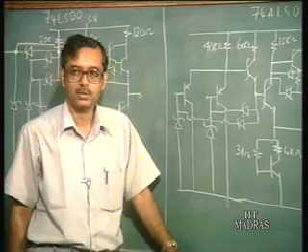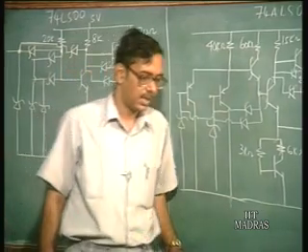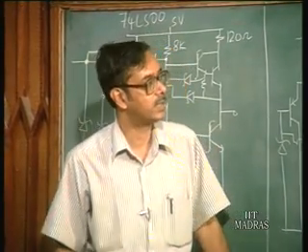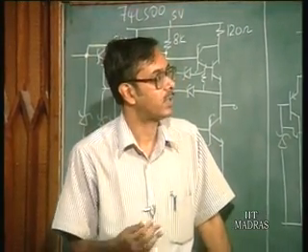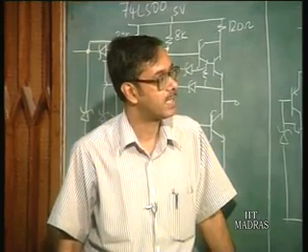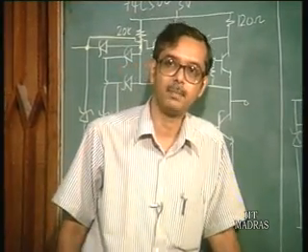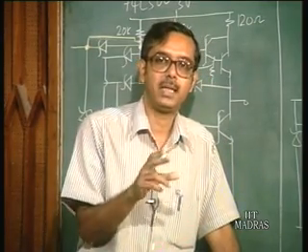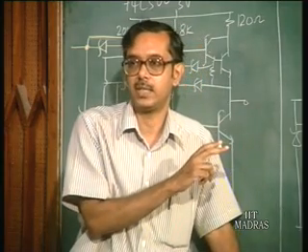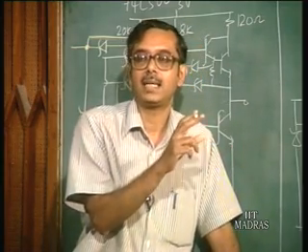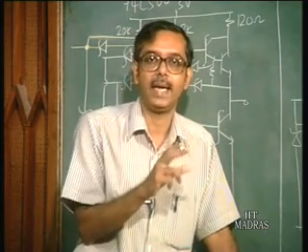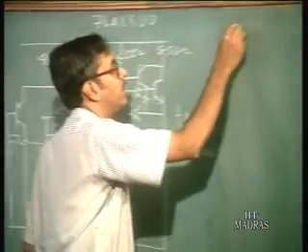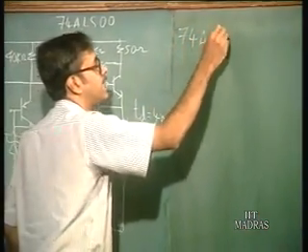It has changed for about 2 decades, and after that, of course, not much has taken place. In fact, the trend has shifted now, in the sense that later there were some 74 series compatible CMOS gates which have come up. They are basically CMOS gates, but with pin compatibility and total compatibility with the 74 series, so you can replace a 74 series gate with a CMOS series gate. They are the 74 AC family, 74 AC or ACT.